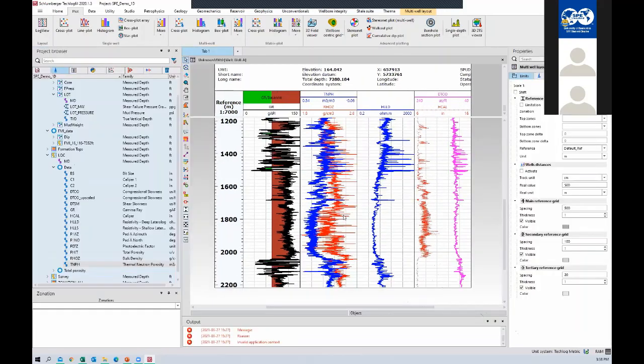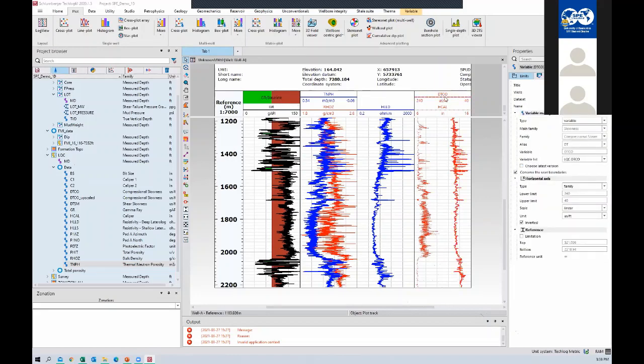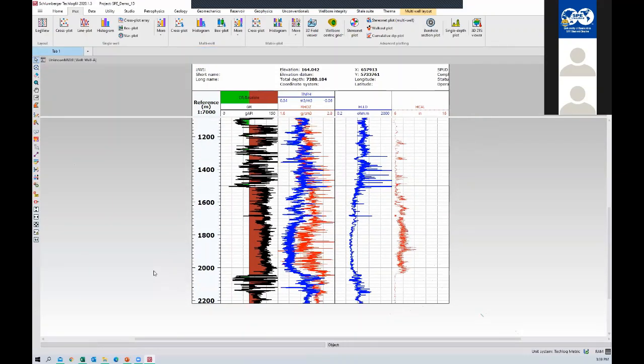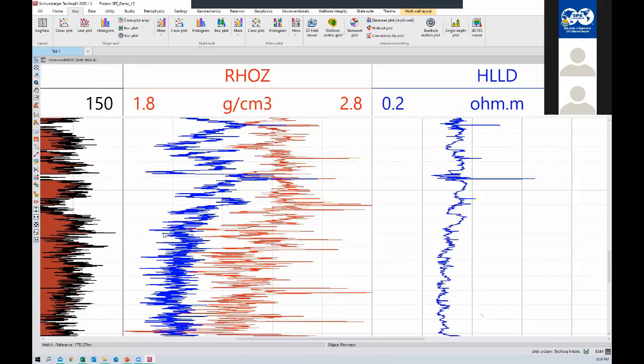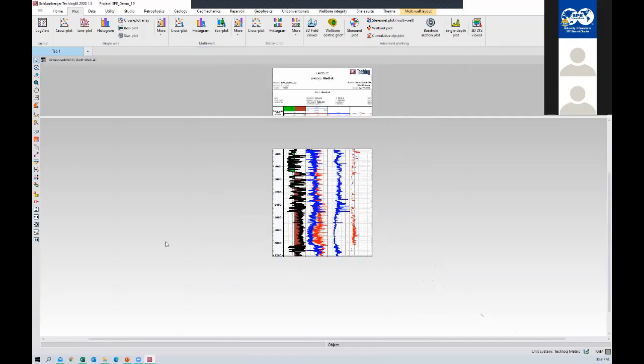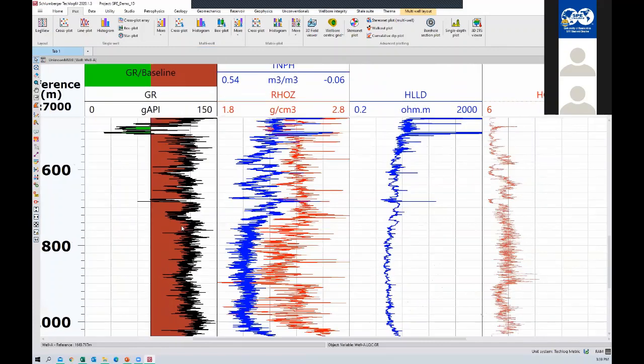Let's say if I want to zoom in. So you see there are multiple ways. Let me show you how you do that. First, let's understand how you zoom in and zoom out. At times you might want to zoom into your plot, right? If you want to zoom in to this plot, what you have to do is press the wheel of the mouse and drag your mouse ahead. Like you see, I'm able to zoom in. And if you drag the mouse backwards, pressing the wheel of the mouse, it will zoom out. So you can zoom in and zoom out, right?